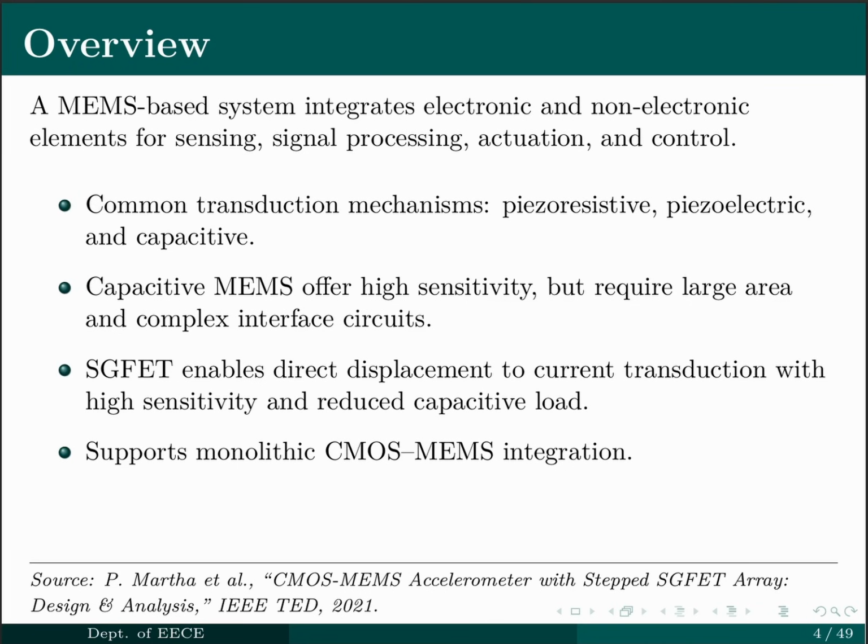The overview is like that. MEMS structures mainly integrate non-electronic and electronic components for sensing, processing, and actuation control. The commonly used transduction mechanisms in MEMS devices are piezoresistive, piezoelectric and capacitive, and among them capacitive MEMS offers high sensitivity, but requires large area and a complex interface circuit.